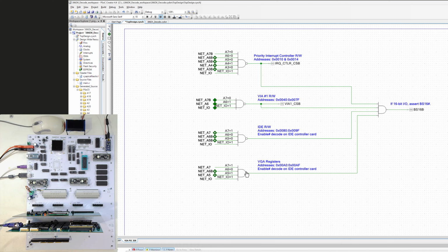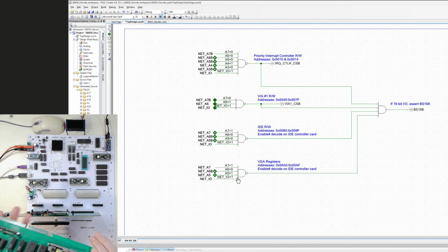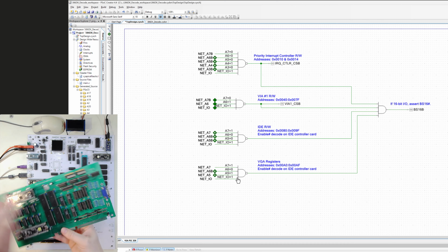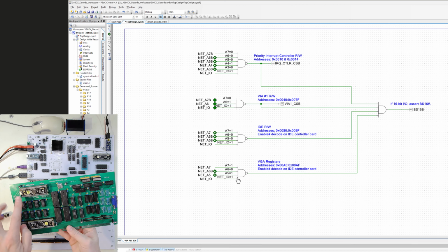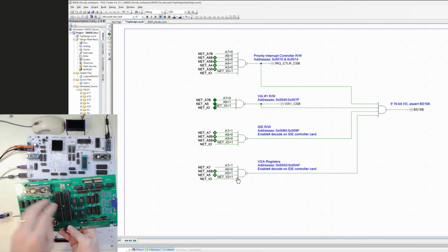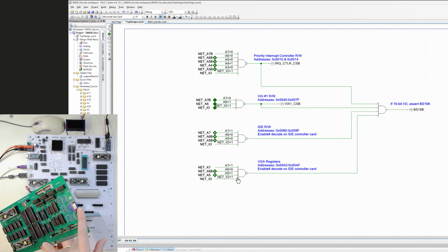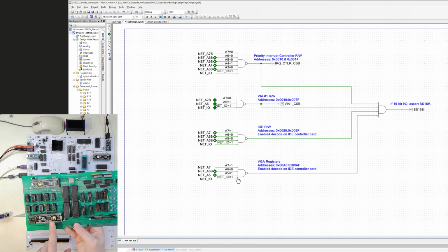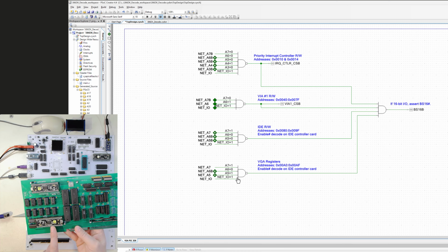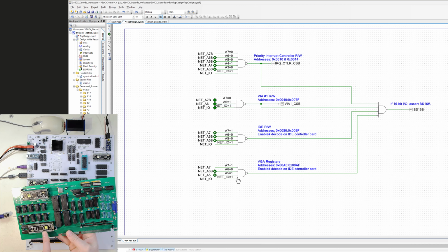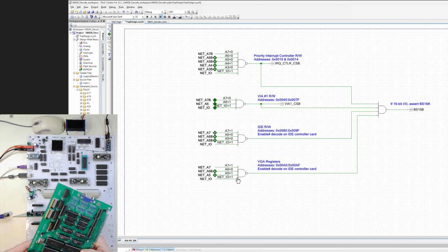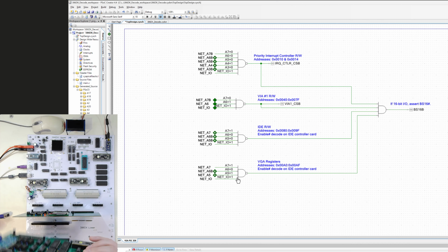When I write IO to that, it goes to the registers. Here on this VGA card, I have this RAM basically that is being used to output. I've got a PSOC that does all the reading of the RAM and sends it out through all of this circuitry to the VGA connector. And then there's also a PSOC for decode. But besides that, I do have just some plain old registers on here. I have some registers that I built in so that I can control which frame is active and things like that. Well, that functionality needs an IO address because I'm doing that through IO to modify the register.